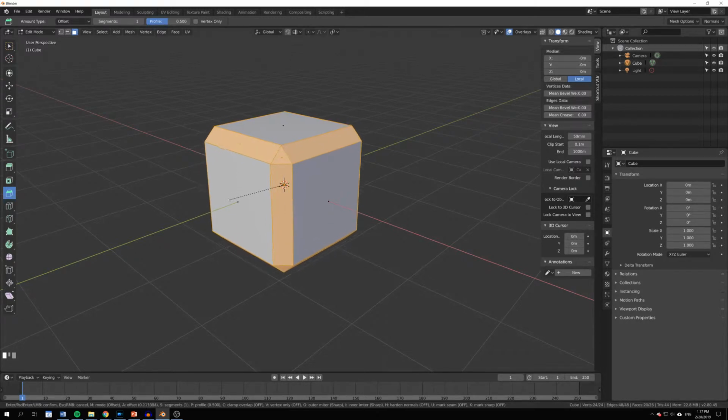The reason for that is that if we have just beveling like this with no lines in between here, you will see that we end up with this triangle. And when we come to the next tool, I'm going to show you why triangles can be painful sometimes when modeling. Though used at the right time, they can be a godsend as well. So don't neglect triangles or what is known as n-gons just because someone tells you that quad faces, like faces that have 4 corners, are the only way to go, because it's simply not true. Triangles have their place, and so do n-gons.